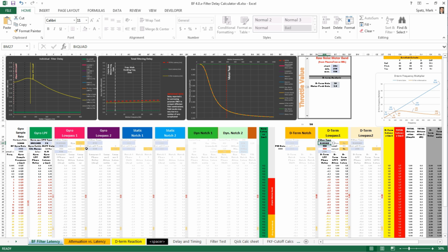Then the P, I, and D terms, all the PID values, won't see any of that noise because the filtering's there on the gyro. And then there's some additional filtering, just because D term is such the bad boy, that we want to counteract that bias towards doubling of amplitude with doubling of frequency. That's where the D term filtering comes into play. And you can split the load too, right? So you could say, well, I'm going to let a little bit more through on the gyro, and then I'll just apply a little bit more on the D term. So instead of delaying the P term and the D term with gyro filtering, I'll split that, and the P term will have less delay, but the D term will have a little bit more because I'm going to put more bias here. So you can thread that needle there.